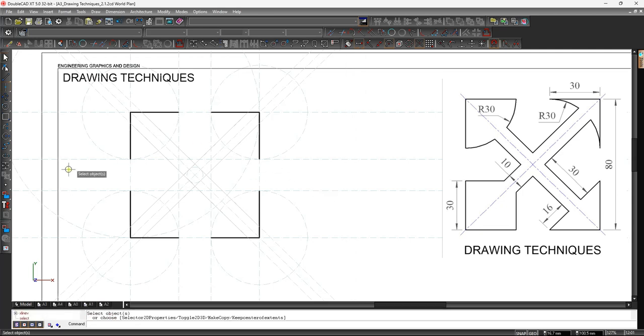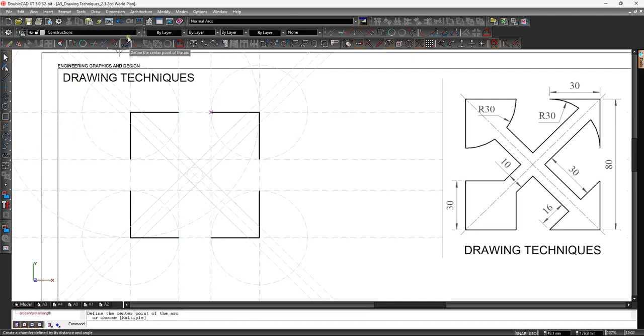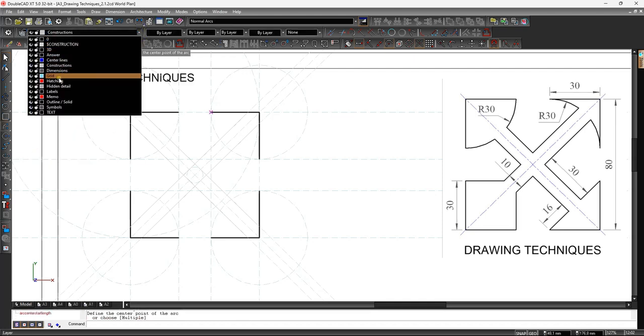I'm going to refer to the reference image again, and I'm going to draw in what I can draw solid from the start. So the first one that I want to draw in solid is with my arc tool, and for the arc tool we go to this selection here, and we will use this one that says center start length, and I'm going to select that, and I'm going to go and select my solids layer now because it's a solid line that I want to draw.